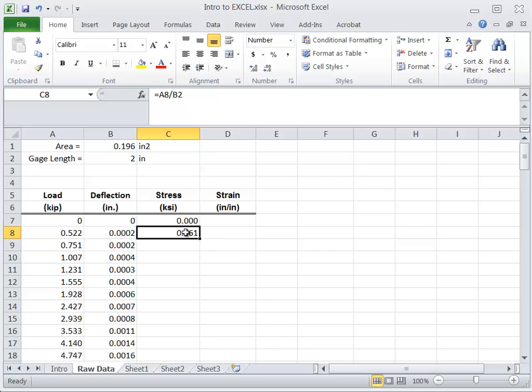And so there is a trick in Excel that we can use to lock the number from updating. It's a dollar sign. So for example here, I want the load to update, so I want the next one to be A8 divided by area, right? So in order to lock that number, I would then put a dollar sign right in front of it, and now you'll notice as I copy down one cell, it updated the load value, but it left B1 the same.